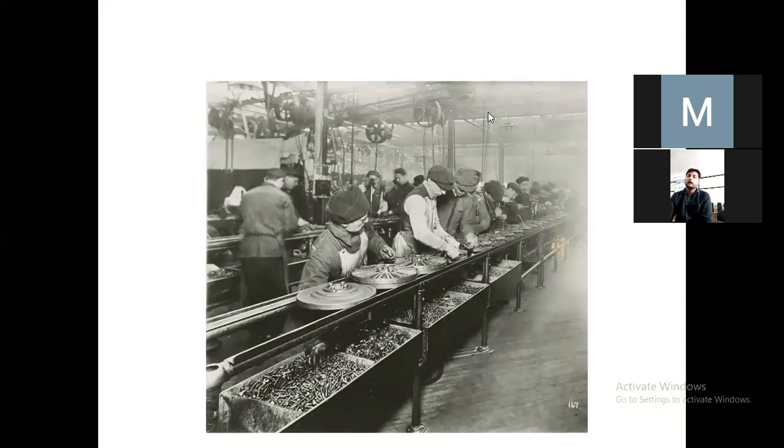Then we have discussed batch type of production, where the product goes through all the departments in a quantity. The layout of the industry is divided into different departments, and the product is transferred after completion of all the tasks in a particular department. Then the batch of product is transferred to another department, and it continues until we get the finished product. So in this manner the product is transferred in the form of batches.